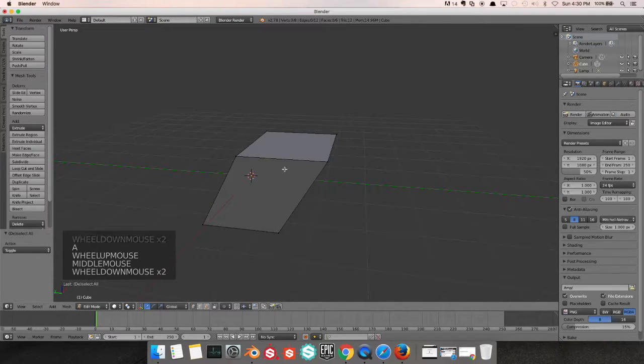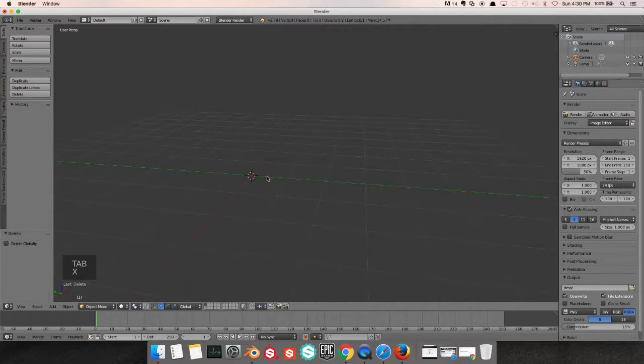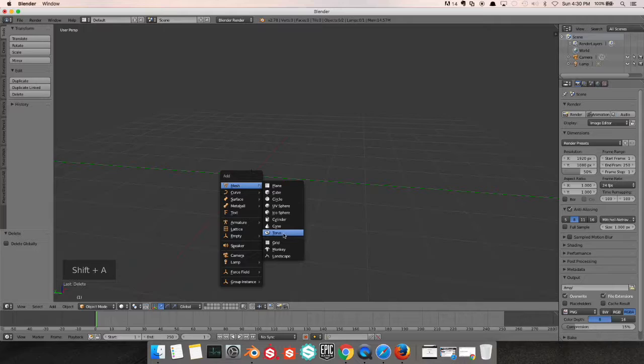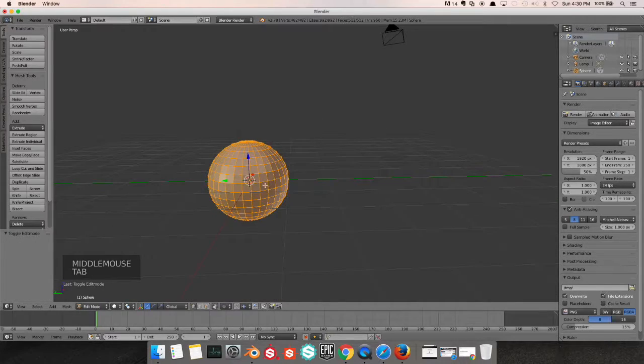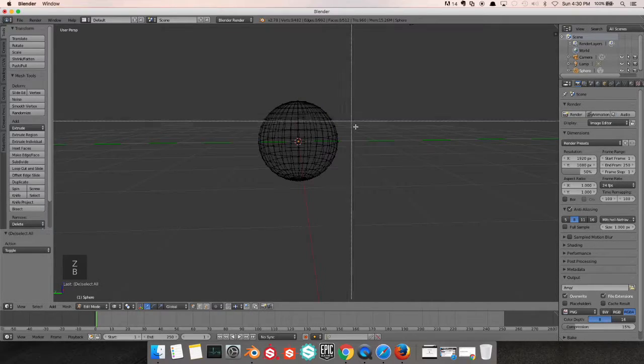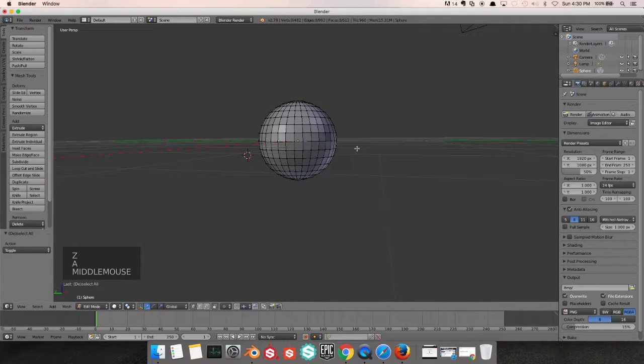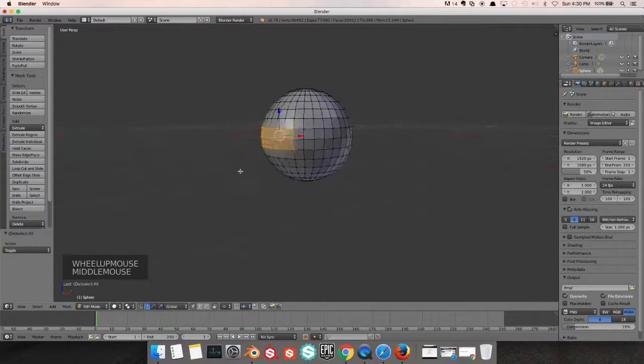One more type of selection mode I'll show you with the sphere as an example. Go into edit mode and then wireframe mode. You do box select, and it's just in a rectangular shape. You're selecting many. And if we're doing box select outside of wireframe mode, it's just going to select whatever is in view on the surface.